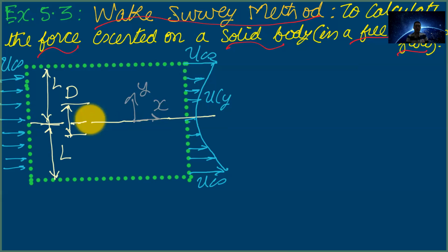To calculate the mass flow rate, you have to do an integral, so you have to obtain the area under this curve. The area under this one is larger compared to the area under that one. You have u infinity only at the ends, whereas you have u infinity uniform everywhere on the complete height. The height of the left boundary and right boundary is the same.